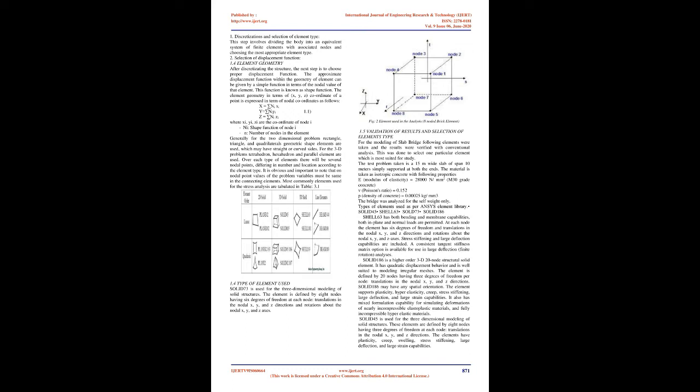1.3 Finite element method. General. For any structural stress analysis problem, the major objective is to determine stresses and displacement throughout the structure, which is in equilibrium and is subjected to applied loads. For many structures, it is difficult to determine the distribution of deformation using conventional methods, and thus the finite element method is necessarily used. The basic idea behind the finite element method is to obtain the solution of complicated problems by replacing it by individual elements or components whose behavior is readily understood. These elements are interconnected at specified joints or nodal points which possess an appropriate number of degrees of freedom.